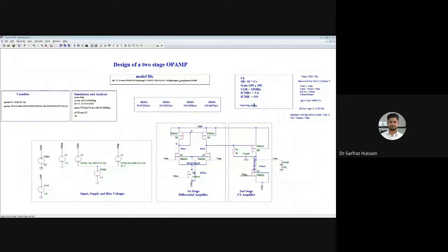For that, the slew rate that we are getting, instead of this I5, I'll use this I7. I will see what the load capacity is over here and apply that particular current, that is, the current required through these transistors. Once I know these, I will design this transistor first and get this value, then I will design this PMOS transistor. So what will be the input? We need to decide that.